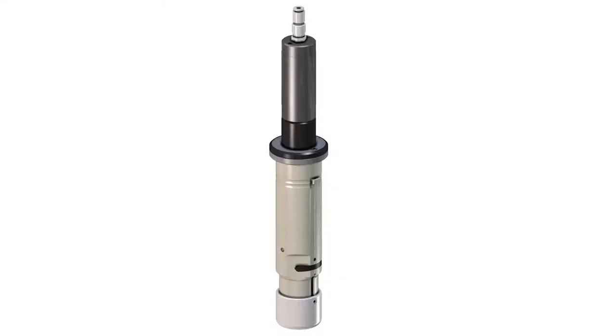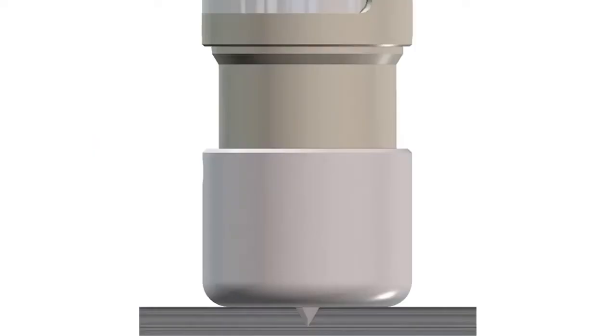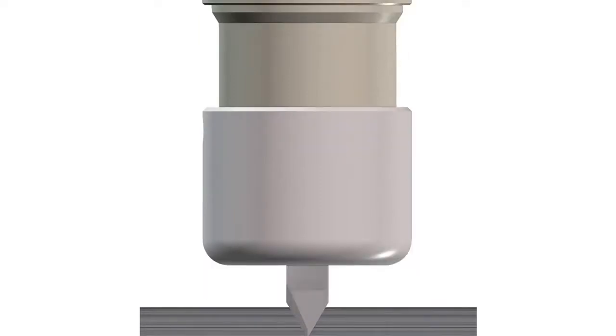The scoring cutting tool is a tool to cut through and score a wide range of materials up to 5 mm thickness. Zund recommends the SCT particularly for processing cardboard and coating blankets. Flat stock blades are used for processing. For scoring, the blade is retracted pneumatically. The score depth must be set manually on the SCT. To cut through the processing material, the blade is moved out automatically.